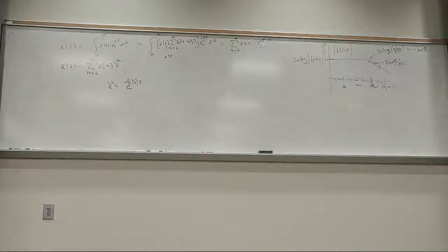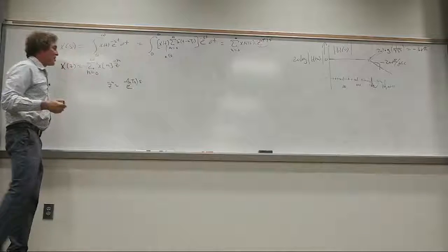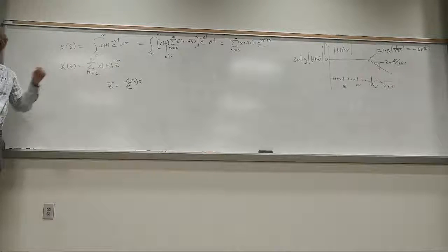Try to appreciate what I'm doing. I want to find a conversion so I can take a filter in the s domain and find a transform for z, replacing s by some transform of z, so I can get this filter and literally have the H of that filter in the z domain. That's my goal. Just work with me on this one. You all agree that if that's the truth, then that exponent, e to the minus nTs times s, has to be equal to z to the minus n. The n can go away. Do you agree with that, class?